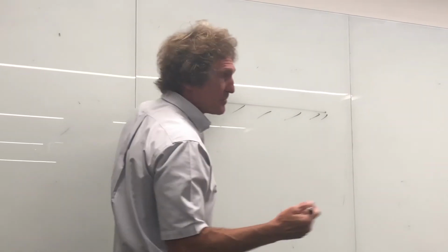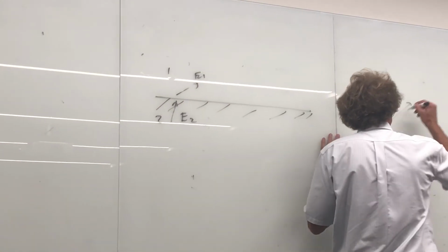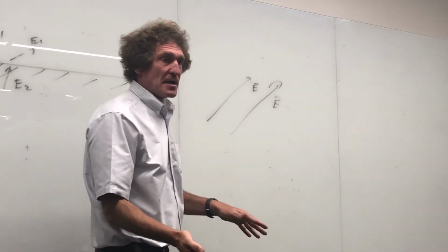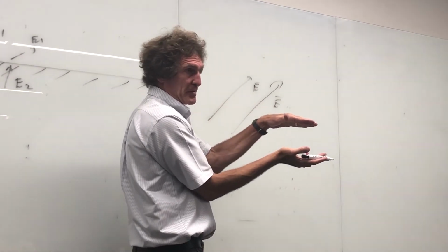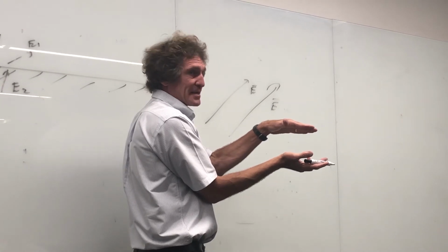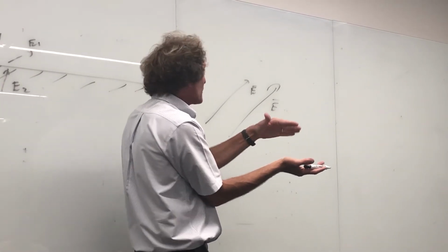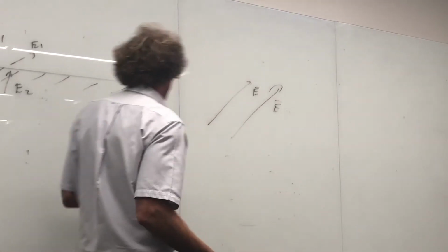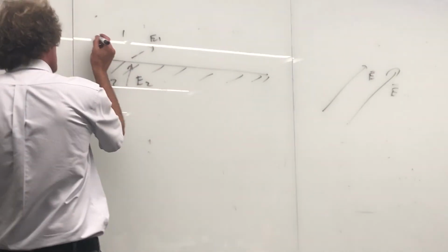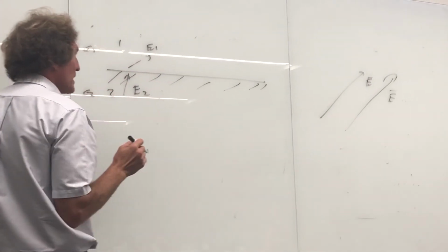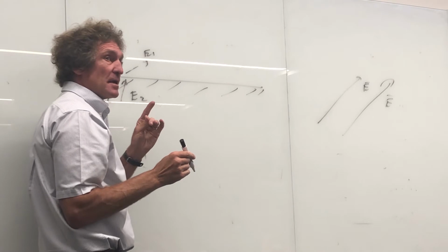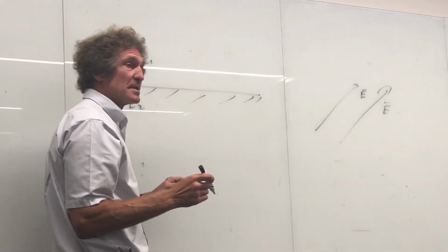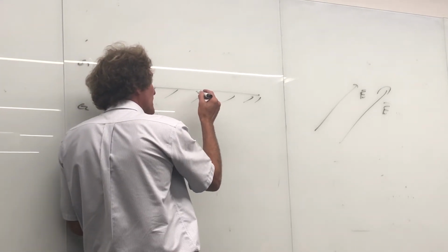It's hard to get a grasp of, but here's what I'm really saying. Let's assume that I have an electric field that looks like that everywhere when no material is present. Now I introduce a material, and for now, don't worry about the extent, assume it's infinite. Above the region it has some epsilon 1, below epsilon 2, 2 different regions with 2 different epsilons. This is epsilon 1, epsilon 2. When I look at this, I'm going to make the case that the tangent E field across both boundaries has to be the same. And here's how they do it.